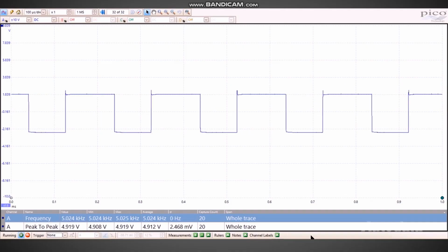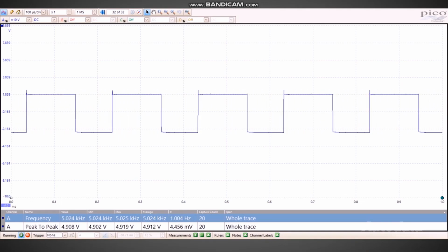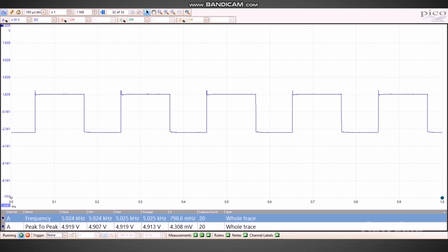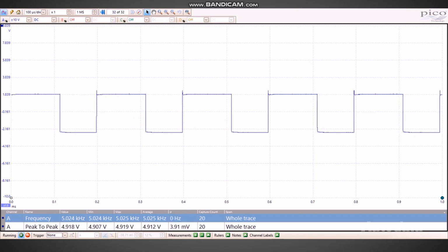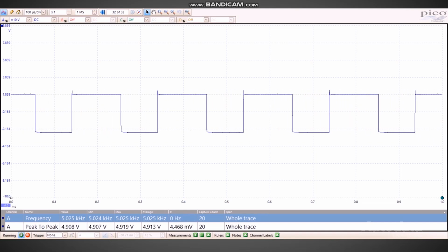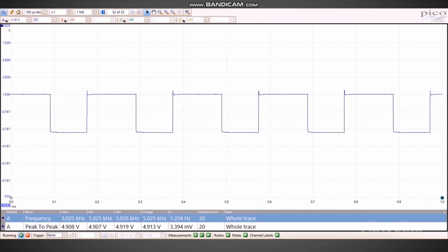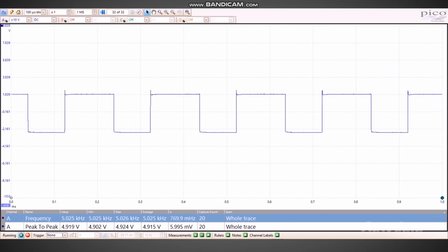Some mass airflow sensors use a changing frequency for their signal. To test these systems, you need access to a signal generator. Apply a signal of 5 kHz at a voltage of 5 volts and observe the scan tool parameter. The scan tool should indicate 5 kHz. If this is not the case and the signal wire has tested okay, then the module will be at fault.